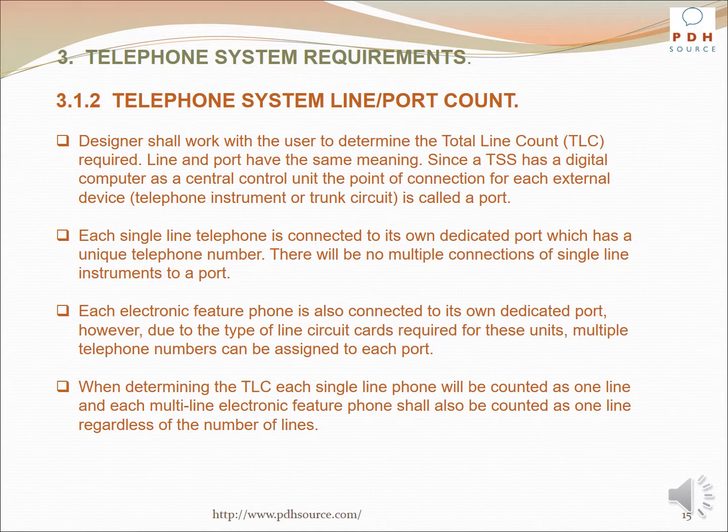The designer shall work with the user to determine the total line count, TLC, required. Line and port have the same meaning. Since a TSS has a digital computer as a central control unit, the point of connection for each external device, telephone instrument, or trunk circuit is called a port. Each single-line telephone is connected to its own dedicated port, which has a unique telephone number. There will be no multiple connections of single-line instruments to a port.